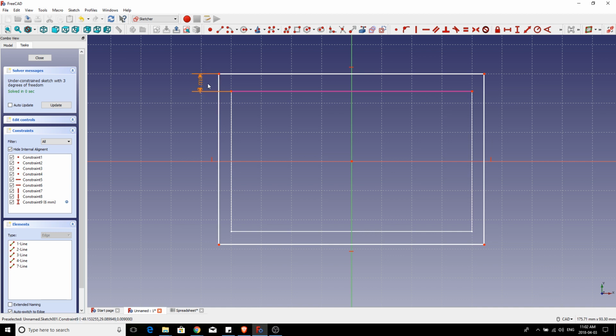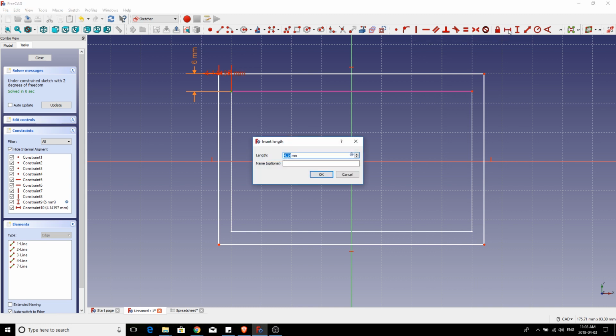And because we've used a formula here, you can see that it's showing up in orange. Now it looks a little hard to read, but if you just kind of grab that, you can pull it until it is looking good. Okay, first part is done. Now we need to create our horizontal constraint as well, which is exact same. Now you'll know you've selected these points properly when they turn green, just like that. And so now let's add in our horizontal constraint.